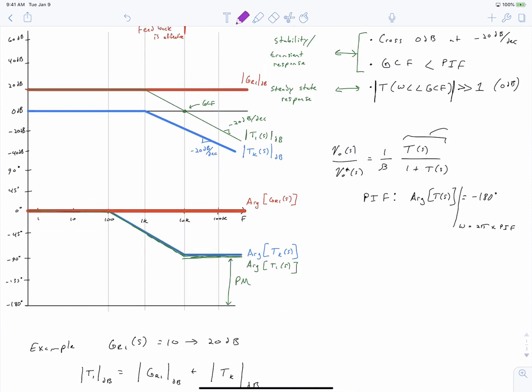Let's take a look at what this looks like. We've got our loop gain here, and 1 is just a plot along 0 decibels. So if we're following the minimum of this, we're going to follow a path that looks like this. Here our loop gain starts to become less than 1, so then we follow it down. And you see that we have the purple transfer function.